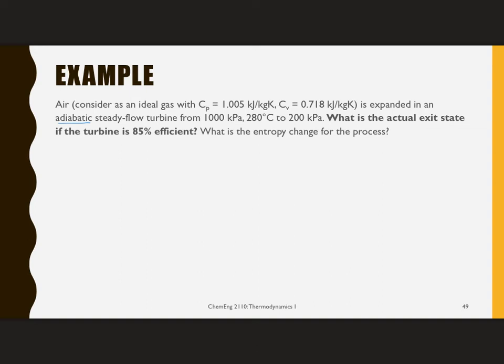This is an example where we have an ideal gas, and reversible and adiabatic is how we begin our calculations. If that's the case, then that is polytropic with the exponent equal to gamma, so PV to the gamma power is going to be a constant.